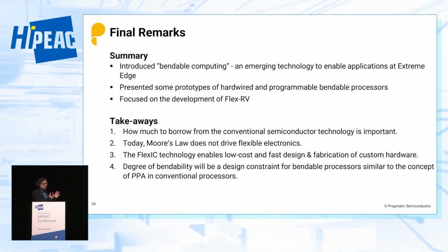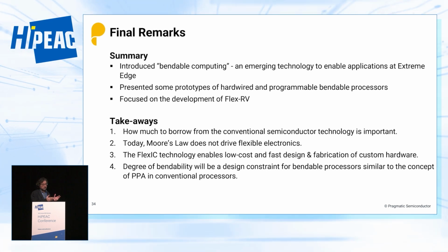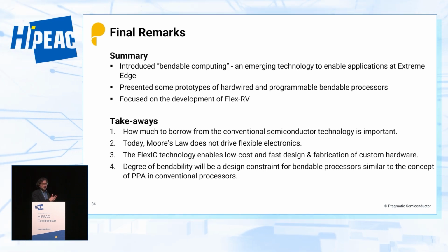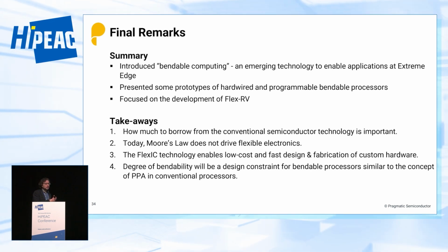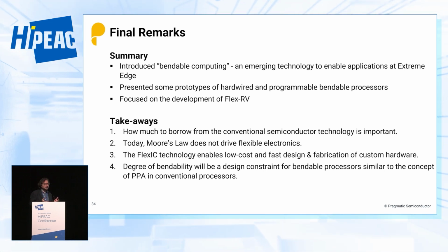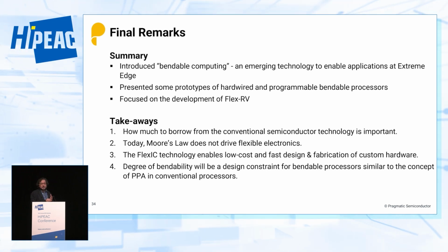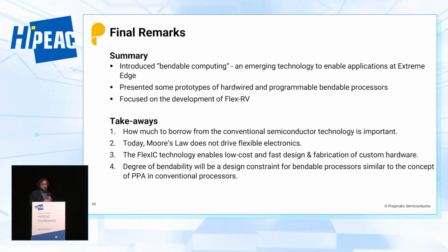We are using 0.8 micron, which is 800 nanometer technology, the channel length of the transistor. Our latest is 600 nanometer. Why are we not going lower? Can we go? Yes, we can. Why are we not going? It's a lot lower cost, and it does the job. When it doesn't do the job, we move. This is our approach.